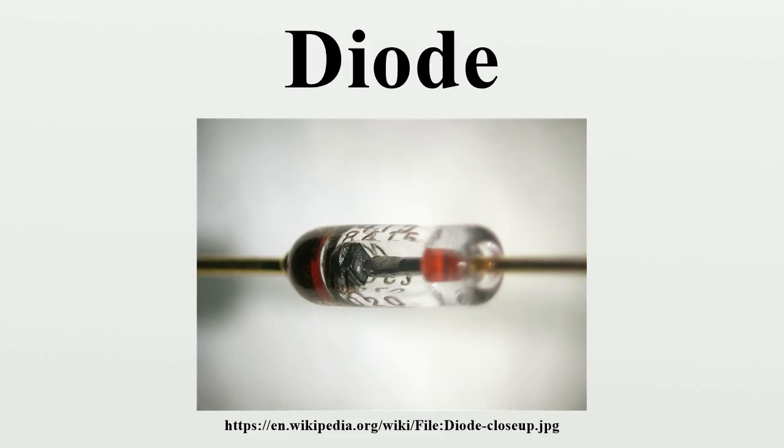A semiconductor diode's current-voltage characteristic can be tailored by selecting the semiconductor materials and the doping impurities introduced into the materials during manufacture. These techniques are used to create special-purpose diodes that perform many different functions. For example, diodes are used to regulate voltage, to protect circuits from high-voltage surges, to electronically tune radio and TV receivers, to generate radio frequency oscillations, and to produce light. Tunnel, gun and IMPATT diodes exhibit negative resistance, which is useful in microwave and switching circuits.